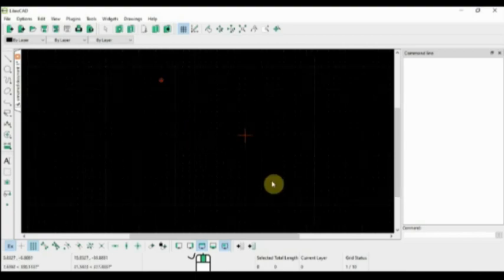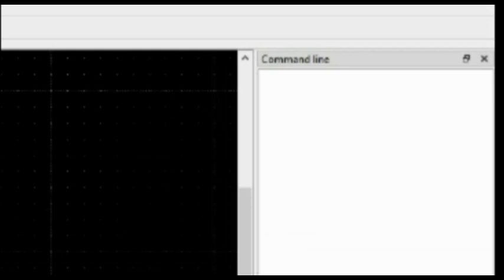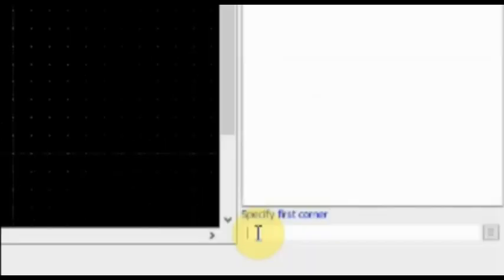However, we are most interested in creating these geometric primitives using the command line. So let's start with the first one, which is the rectangle. We're going to use RECT for rectangle. So we can give coordinates from 0, 0, and that is the X and the Y. And then we can have the second one as 5 and 9. So this one gives us this particular shape, which you see in there, a rectangle.